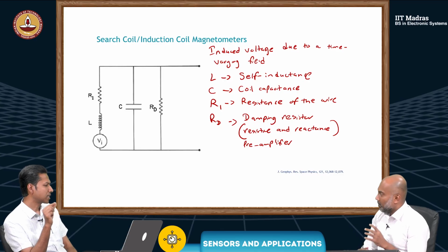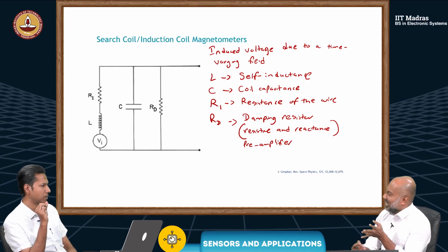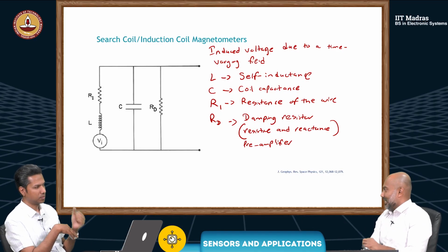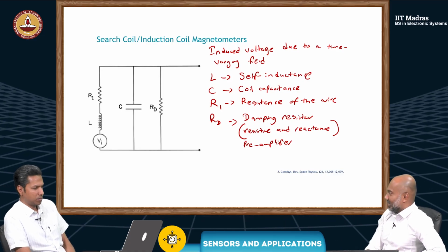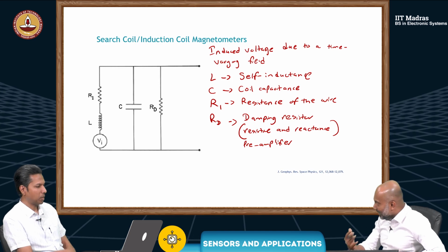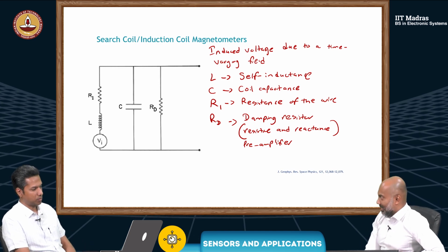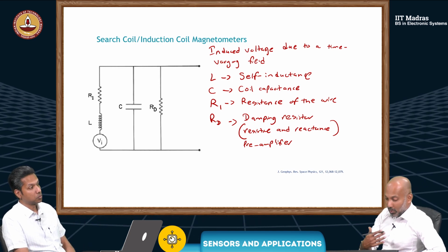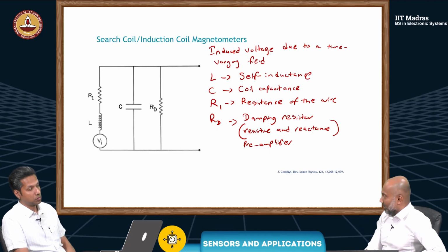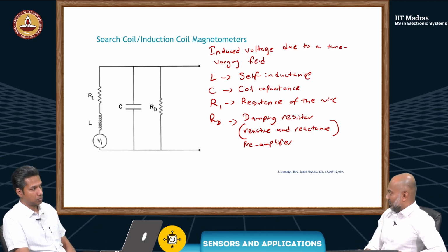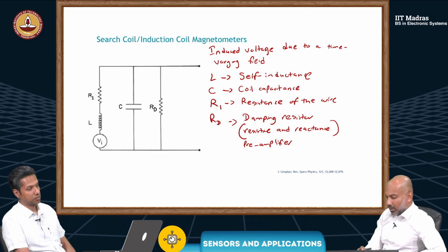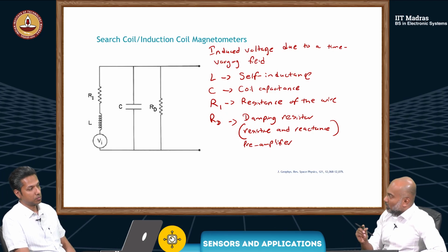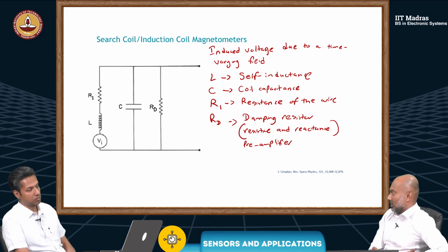So then it's not just a resistor, it's an impedance. It really should be Z, no? Yeah, really should be Z. But let's say it's representing the resistive and the reactance component. Ideally, it will be dominated by the resistance. But now we know, because there's R, L, and C, there's going to be some resonance. Possible, yes. And do you think this RD can somehow tune the sharpness?